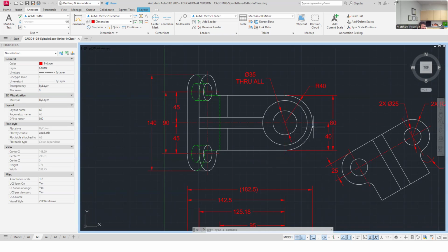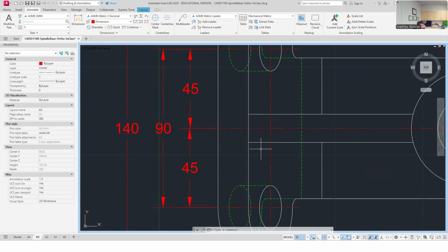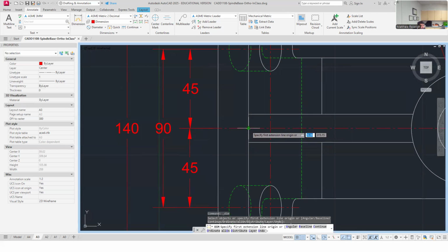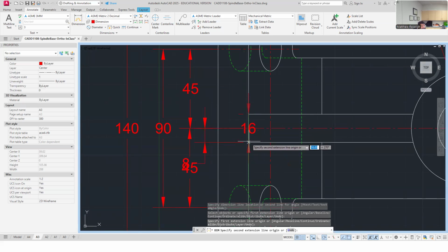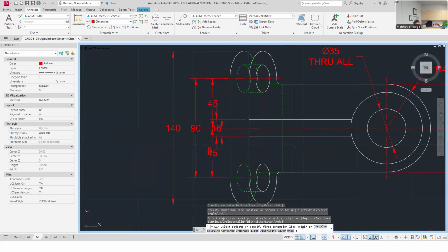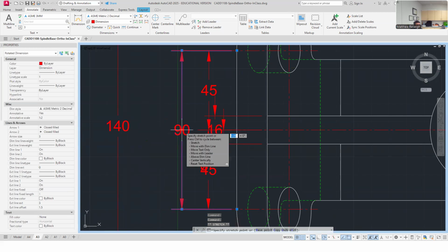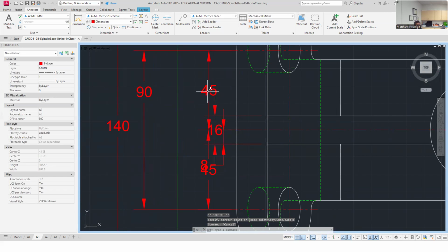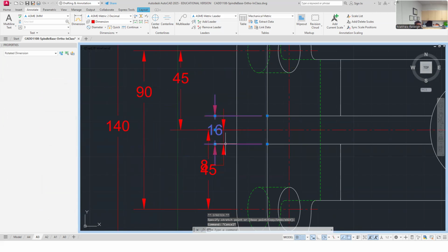I actually dropped that dimension, but I just wanted to bring up that argument and beat it to death. So there we go. I think I've covered that part. Now let's move on to the gusset. It's the last one. And yes, what Sky said a while ago was that I need to dimension it right here, and I'm going to dimension off center here. So in order to place that gusset in this view, I'm going to say it's 8 off center, and then I'm going to have this 16 overall width. Kind of like a keyway in a little bit there. I'm just basing its size and location. 16 is really the size. The location is 8 millimeters off center, not inches, but 8 mil. Yes, I think we'll say 8.